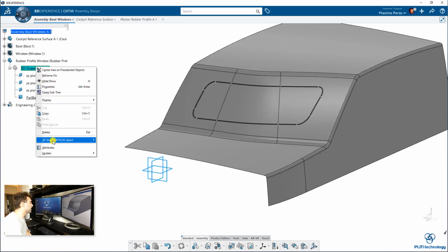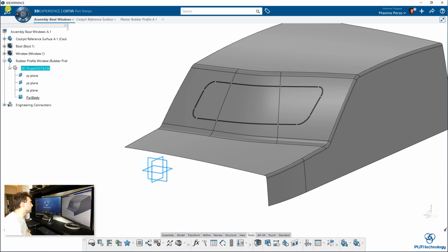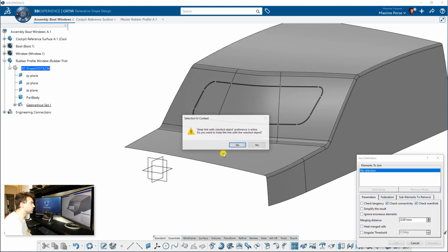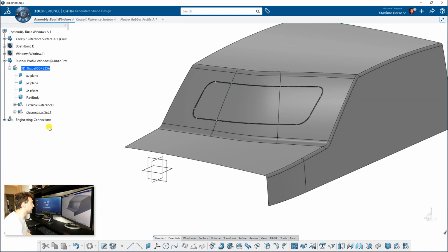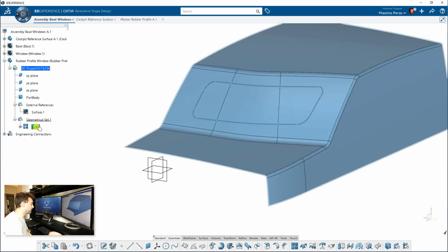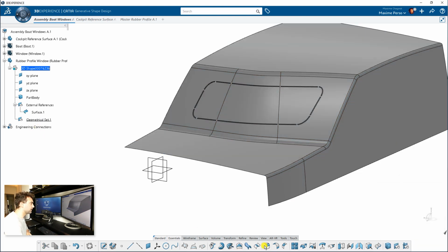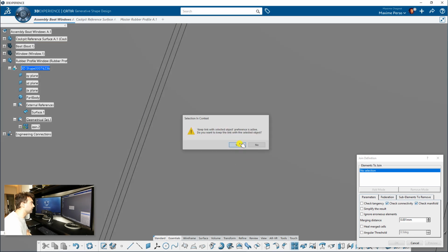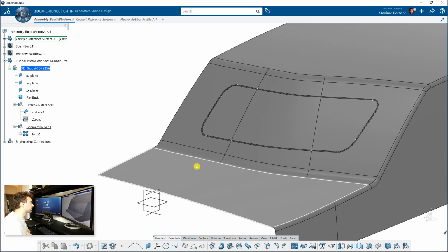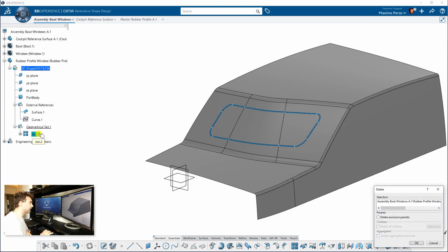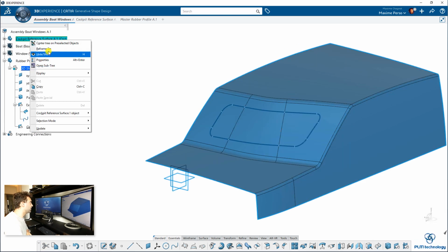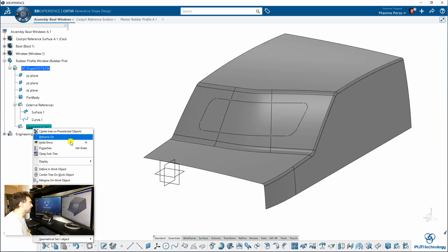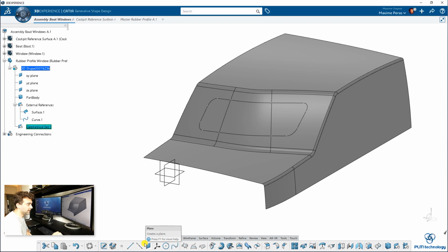So you go to the 3D shape, we can switch back to generative shape design. We can do the technique I gave you, the join here, okay. So you can delete the join and keep the surface, and we do the same with the middle contour this time. Okay, and delete the join again. I can hide my copy because we will not use it. And I will add, of course, a point and a plane.